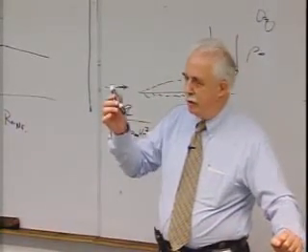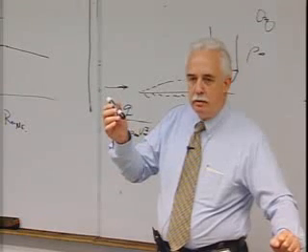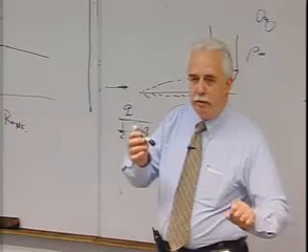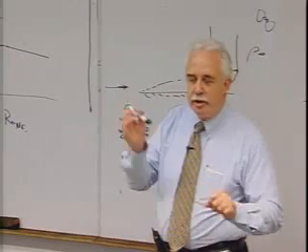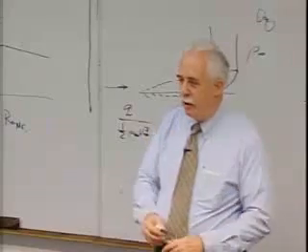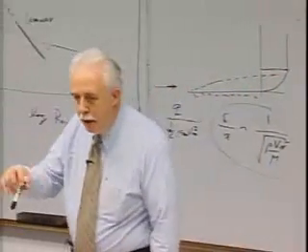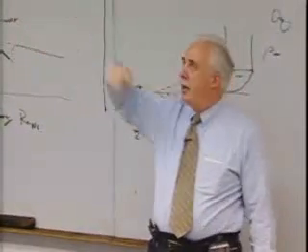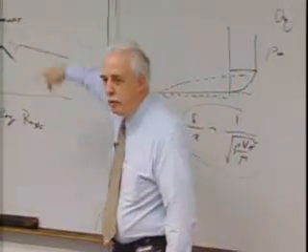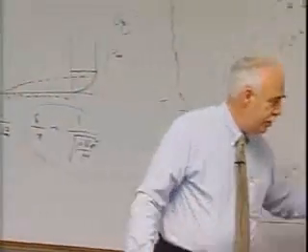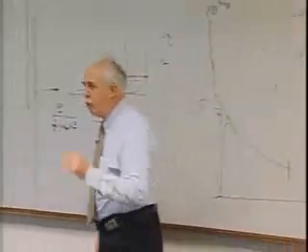But what happened was the booster lined up with the wake of the incoming test vehicle and just rode the wake because there was a lot less resistance with the air that's being sucked along with it. It clobbered the back of the vehicle and it nutated. And so we weren't looking at the stagnation point, we were looking off at 30 degrees. Not only that, but the radiation was doing this, okay? We figured out the problem, sorted it out, had a second flight test, and it worked beautifully.